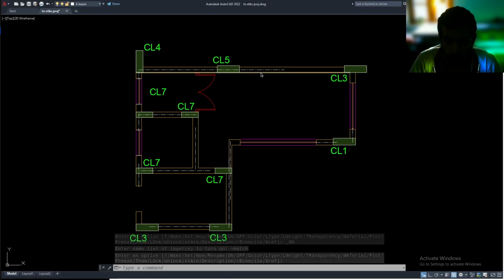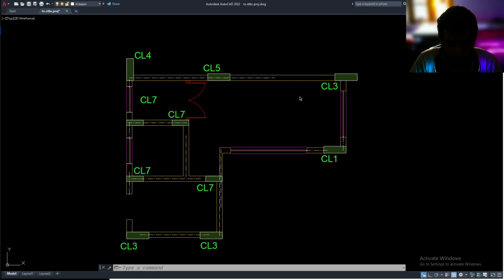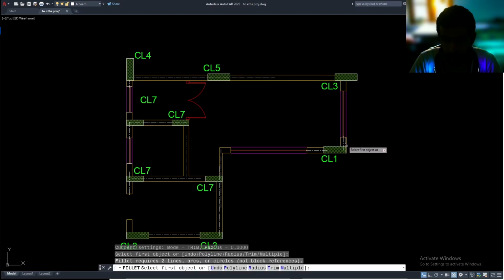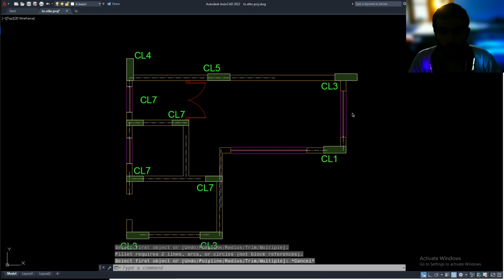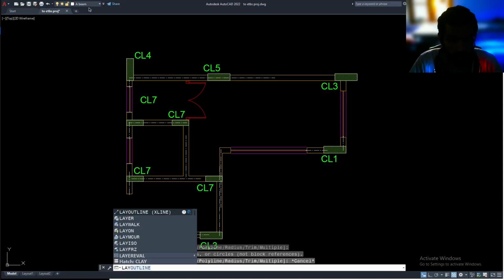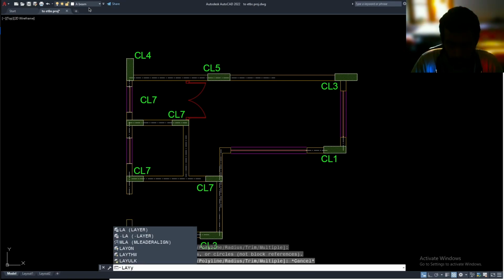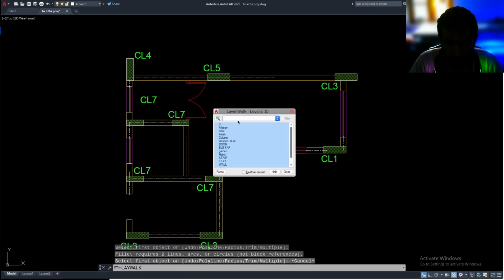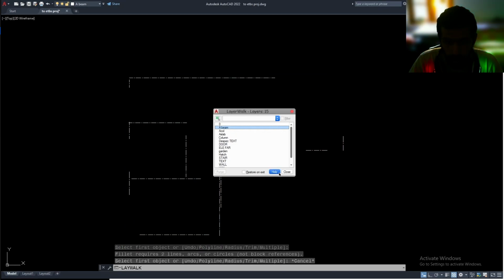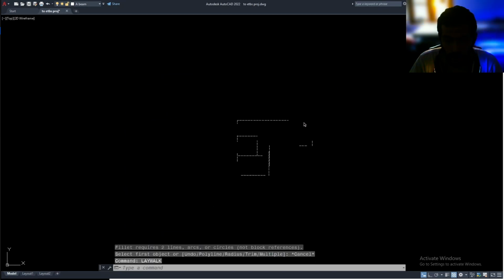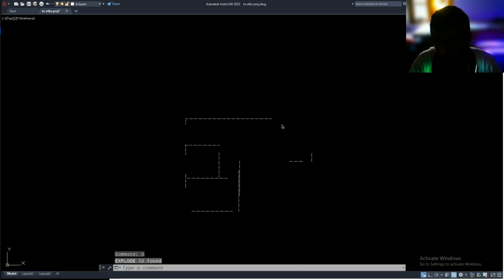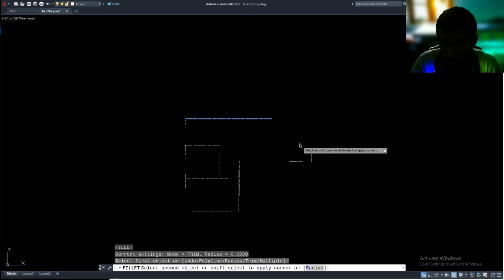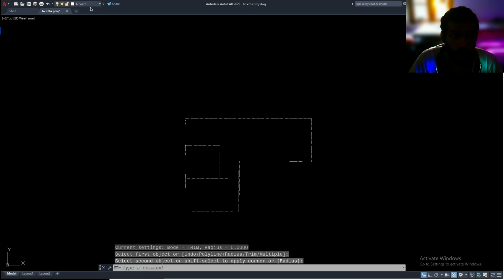What we want to do here is have a corner here, but it's impossible to fillet the center line. So if I try to select these 2 lines by making use of the fillet option, it cannot be filleted. So I would like to get into layer walk, and now pick up this layer and close it. I'd like to explode all of these lines so that I can fillet them. Fillet, first one, second point, you can see that. Alright, LAYON.